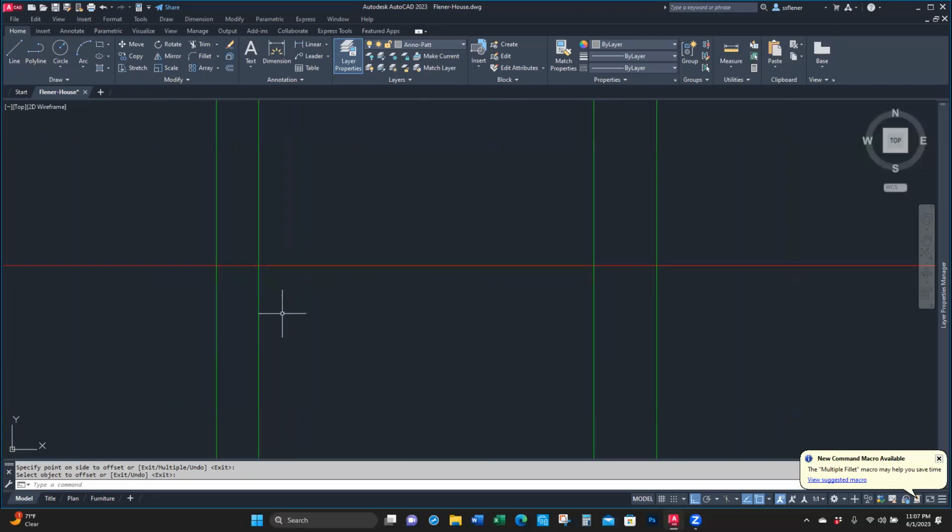And we're going to, so a pocket door has a little metal thing that has a groove in it that you can use your finger to close the door with. So we're going to offset 0.5, this center line up, the center line down. And then we're going to erase the middle. And we'll fillet the corners here.